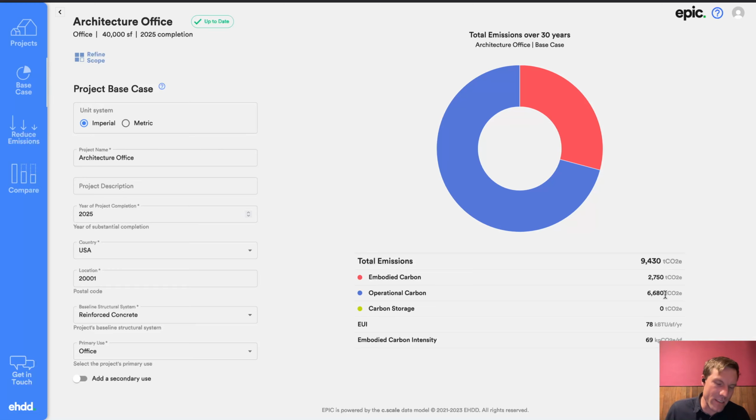So this tells us that concrete, which is the major structural material in this baseline building, EPDs that are available in the Washington, D.C. metro region have a relatively lower carbon intensity than those I'm seeing around San Francisco, and that the grid that we're connected to in D.C., which I think is PJM East, has a much higher carbon intensity into the future than that we're seeing in California. So again, really strong effects of location in these models. We'll move back to California for this analysis, since that's where I am now.